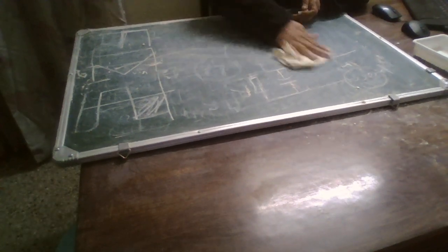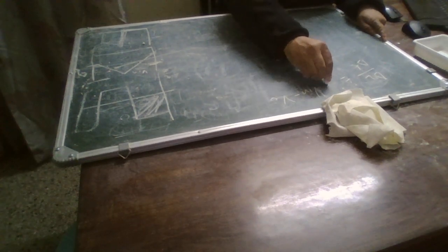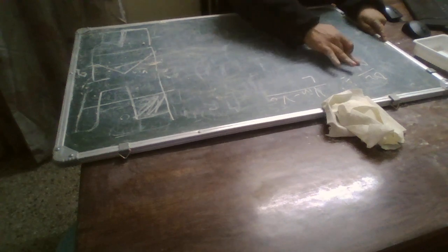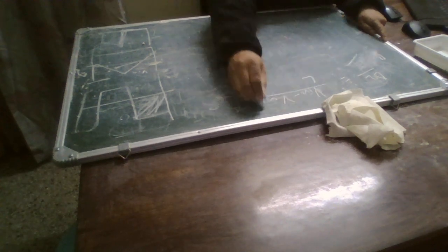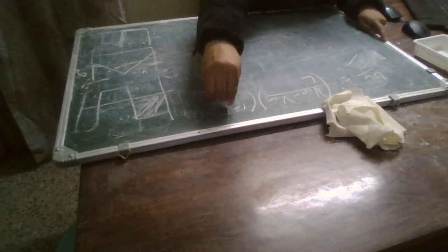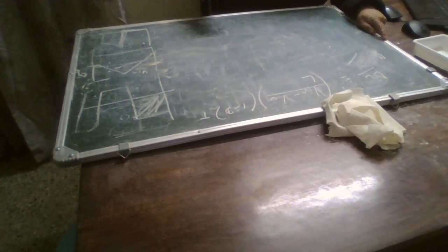So rearranging it, we get delta IL upon delta T equal to V input minus V output by L. And here this delta T is 1 minus d, then T. So this is the inductor current during the switch off time period.